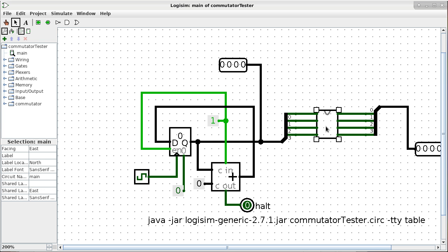So when you increase everything to 7, that means the register here has to be 7-bit wide, the adder here has to be 7-bit wide, the output pin has to be 7-bit wide, and then these wires will all be different because you have to bundle 3 into X, bundle the other 3 into Y, and then the one left over is going to be K0. So all of those would be your input pins to the design that is being tested here.